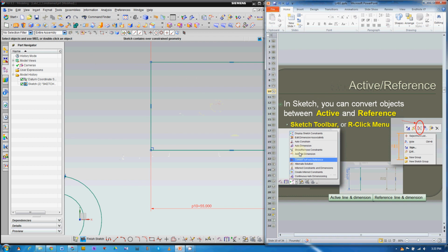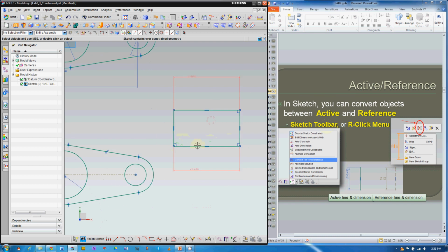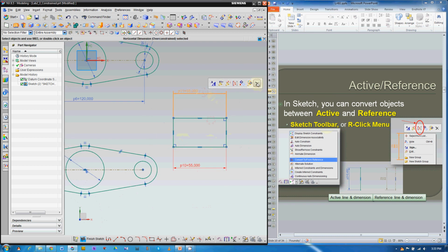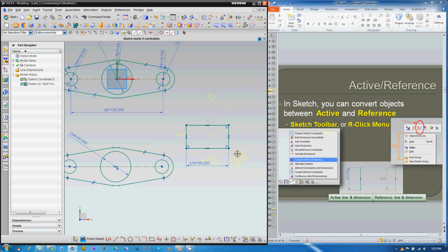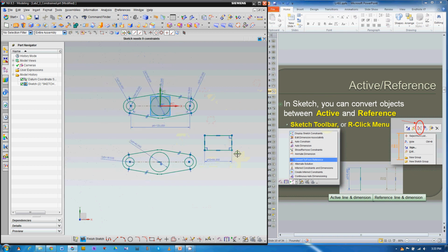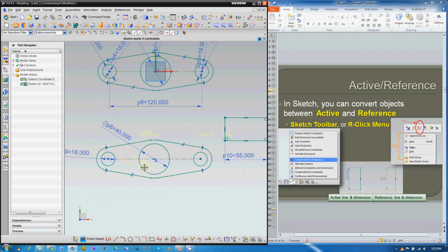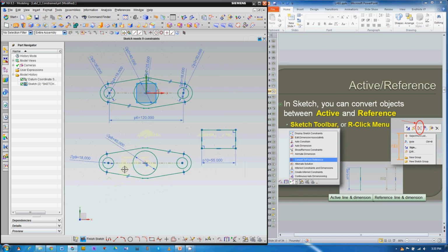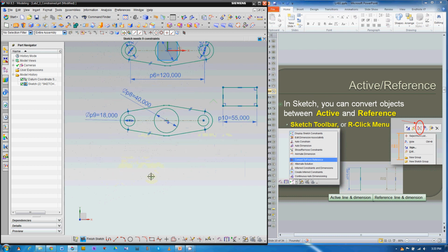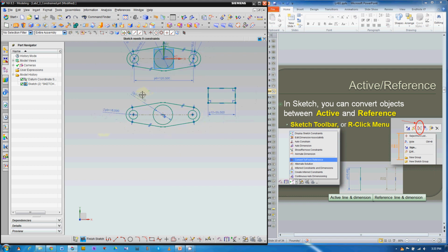Let's come down to reference and active curves or dimensions. I believe if you have used Pro/E, you can actually draw reference lines. But in NX, something like this would be much more convenient if I have this reference line first, then I draw the two circles on the end points of this line.